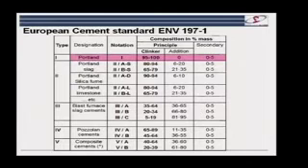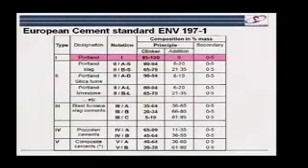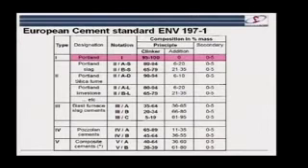And finally, we come in Europe to what we have in the European cement standard, the European cement norm, and it looks really complicated. You don't need to remember all this, but what's important to see here is that this norm has been arrived at precisely to better be able to use these composite cements, these cements where we're adding in fly ash and slag and limestone. So as we go down, what basically changes is the amount of addition. At the top here, we see the CEM I, which is basically 95 to 100% clinker, with sulfate, of course.